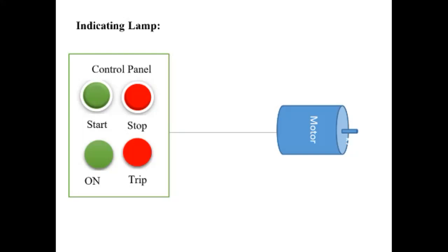Green usually indicates the safe condition, that is, the power to the motor is off, brakes are on, etc. And amber indicates conditions that are important but not dangerous, that is, fluid getting low, machine pause or machine warming up, etc. Some other colors indicate information not critical to the safe operation of the machine, such as time for preventive maintenance, etc.